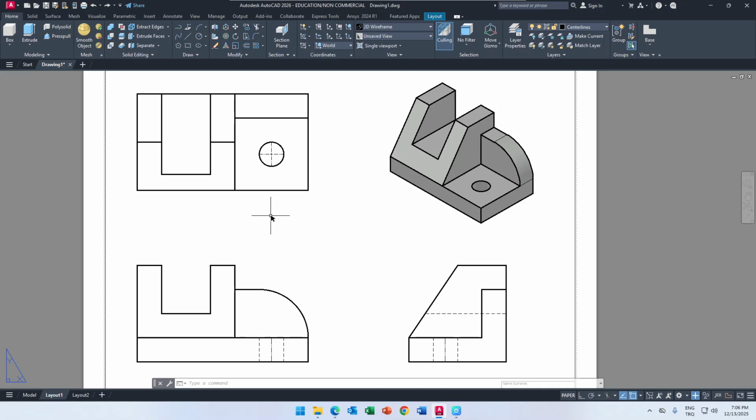Make sure that your style is conforming to the standards or my video, and then make sure that your dimensions are appearing here well without any more trailing or leading zeros or additional dimension application or the unit application there.